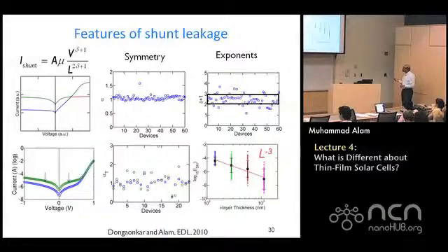I believe this is also 60 devices, right? Or is it 400 devices? 280 devices. So this is based on 280 devices with different I layer thickness. This is the region in here. Again, you can get approximately a 1 over L cube type dependence, showing that this type of shunt conduction is parasitic, but at the same time can be accurately and quantitatively described.